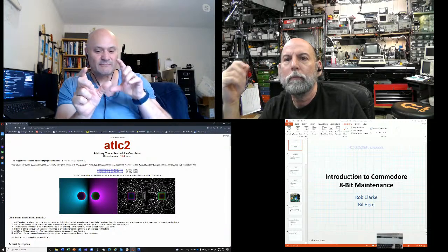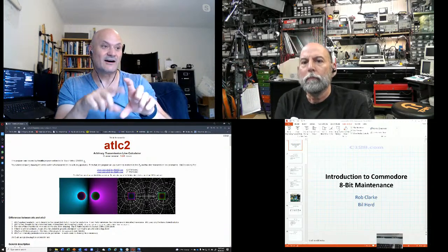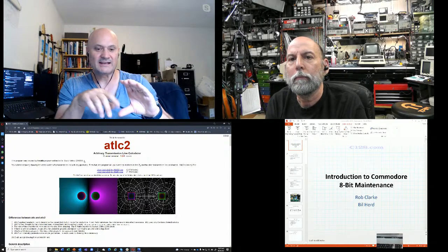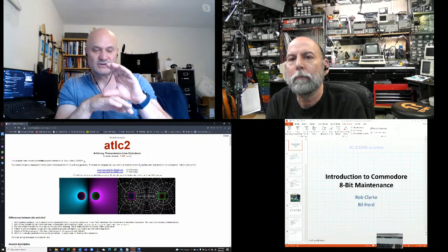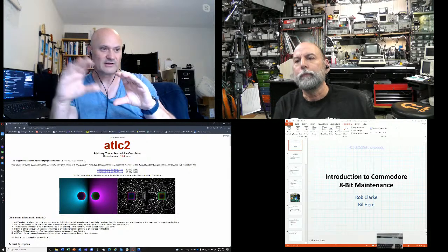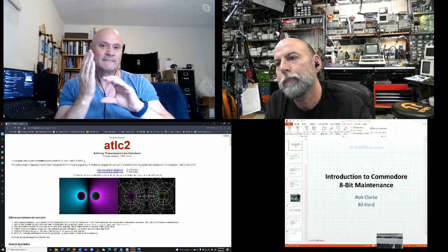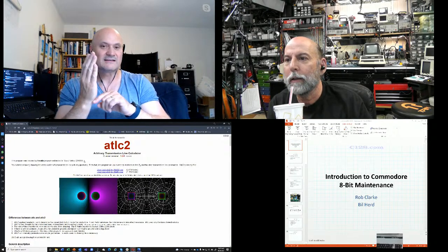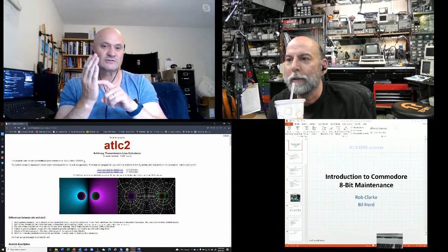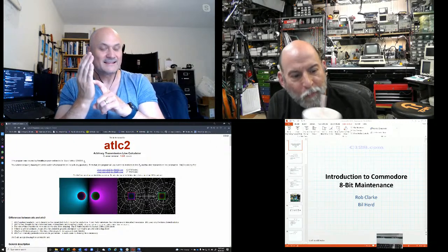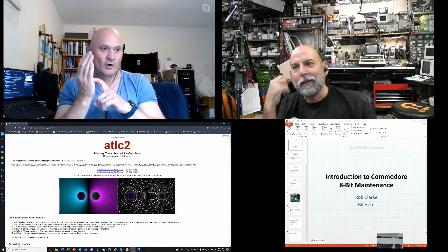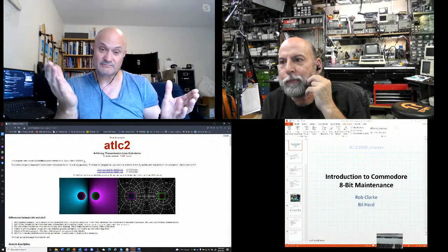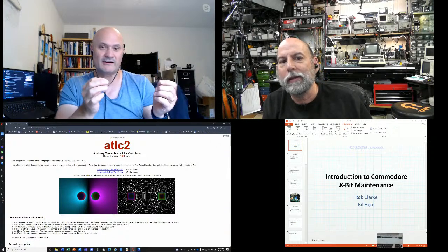But that voltage source, which is theoretically ideal, an ideal voltage source provides voltage, and it will maintain that voltage no matter what you attach to it. So even if you put a dead short circuit on an ideal voltage source, it's still going to have that voltage. And so one of two things is going to happen. Your short circuit cannot exist, or it must have some resistance, which we know is true because even a piece of wire has resistance.